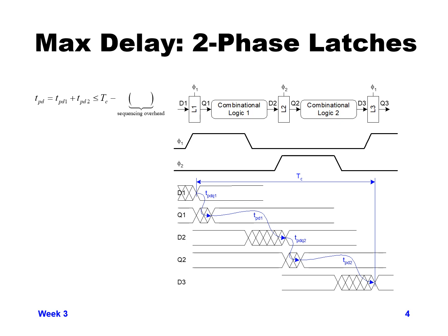And then we go through latch 2, assuming that the time to get to D2 is after or approximately where latch 2 is open, or maybe even a little bit after latch 2 opens. Then we aren't slowed down by the clock switching because the latch is already open.